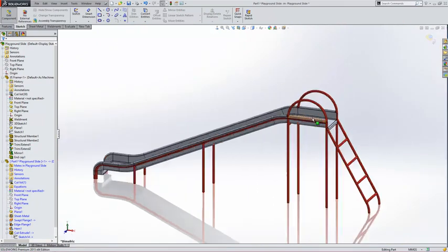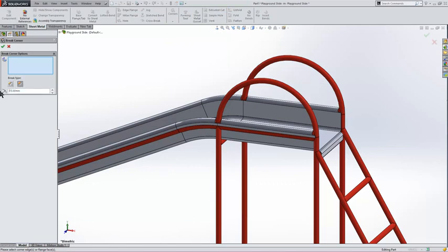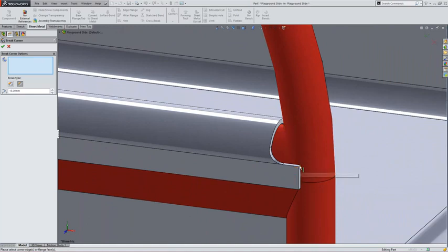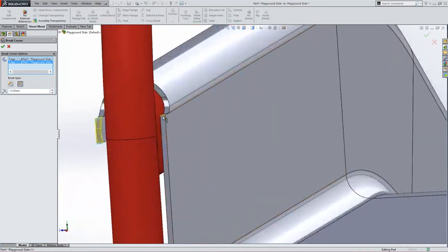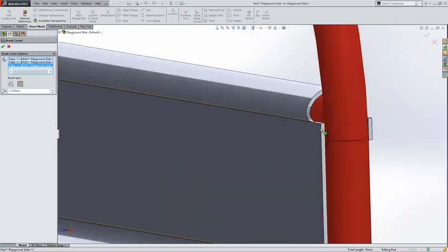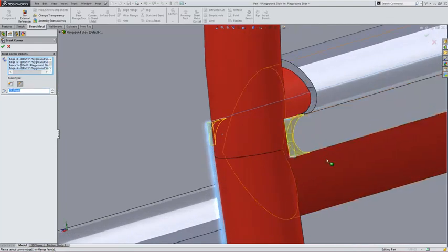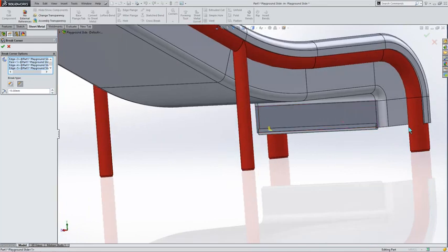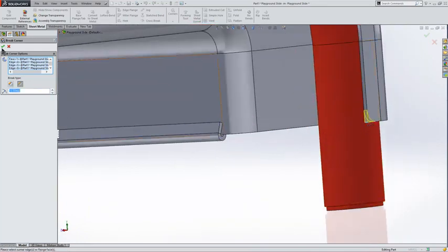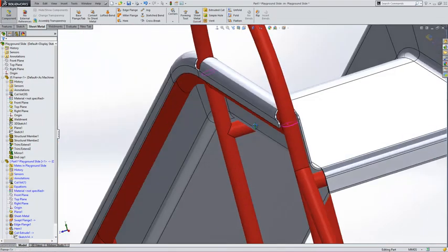Now we can add one last feature here, which is called under the sheet metal, it's called a break corner. We'll have a radius of say 15mm again that we can apply to these really sharp edges that are around here. Like so. Okay. Now we don't have to select edges, we can select faces as well. This face is not going to enjoy having both corners done, so we'll just leave it like that. We can also apply them down the bottom here. And give that a green tick. And we've got our really nice corner that we can actually not cut ourselves on.